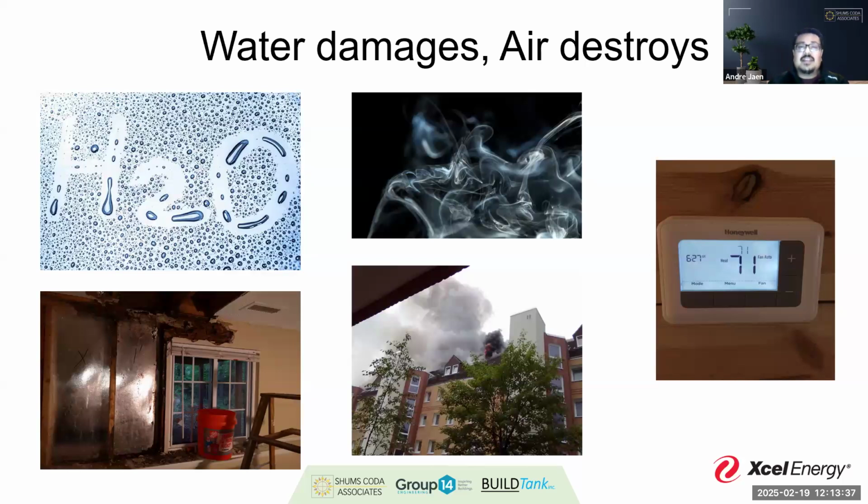But you can also see that this is some of the ways that we promote safe and healthy buildings through a life safety component, right? Air barriers help prevent the transmission of hot gases and smoke from one compartment to another within a building, like this multifamily building suffering this fire right here. We can also see different fumes or gases that might typically be present in things like a residential building. So the way that we separate our garage space from the rest of a building is imperative because it's built on an air barrier fundamentally.